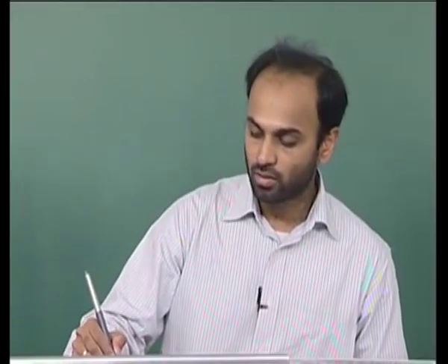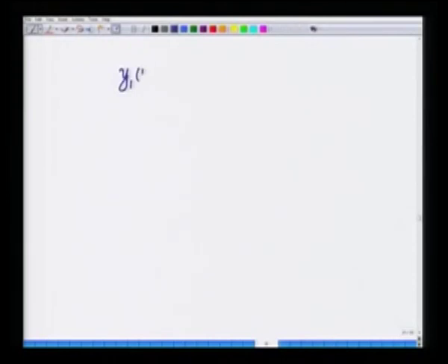Similarly, the signal corresponding to the first path can be written as the real part of a_1 s_b(t minus tau_1) e to the power of j 2 pi f_c (t minus tau_1). All right, so this is the response corresponding to the second path.